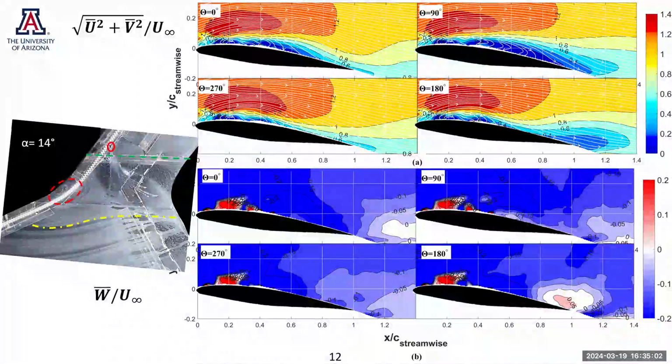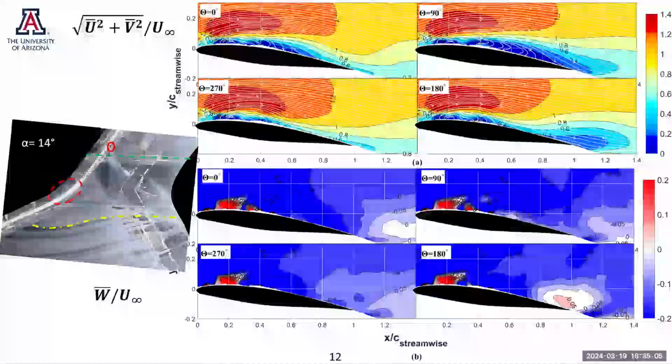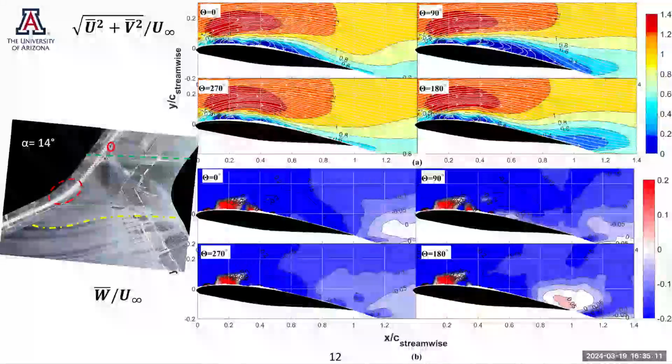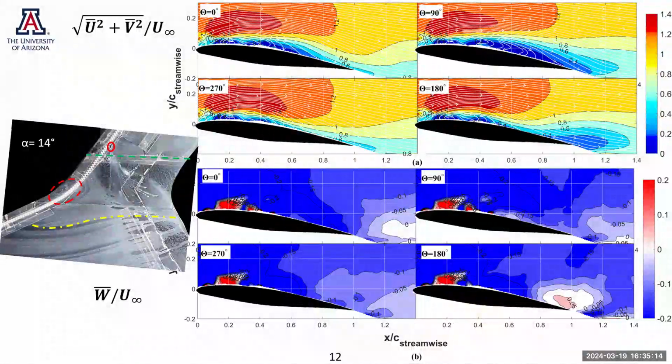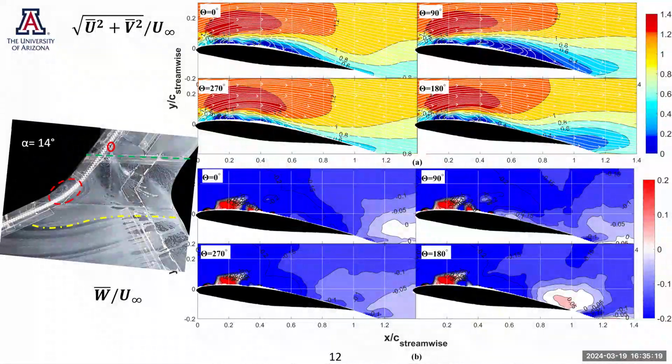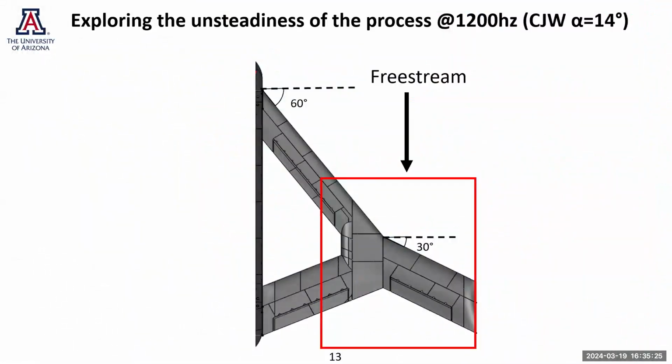that the interaction between this structure and what was happening downstream of the jet was effectively eliminated by introduction of this steady jet. You can also verify that from the oil flow, where earlier we had these entrained streamlines that are not curved right now. So we see from the ensemble averaged and non-time-resolved data that there is some periodicity in the flow that we would like to investigate more, but because of lack of high-speed PIV, we did some non-traditional approaches.